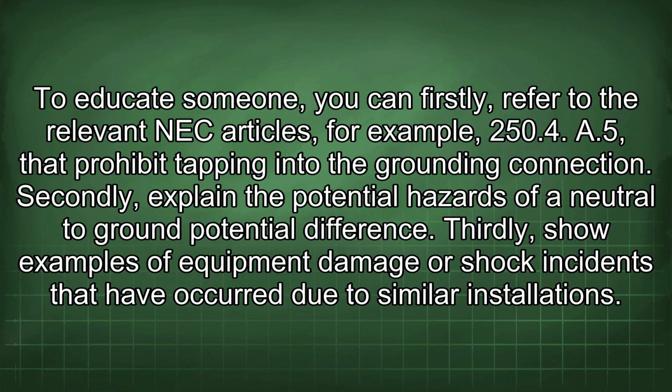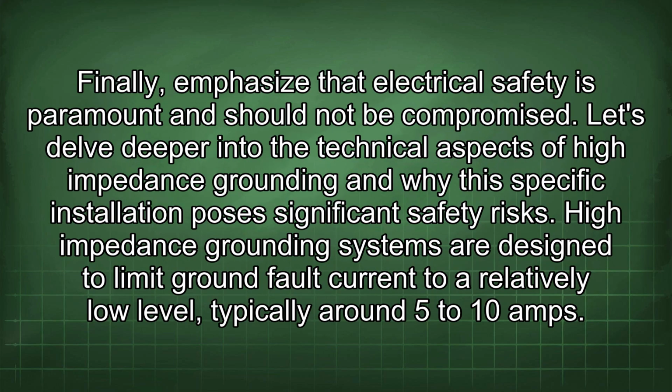To educate someone, you can firstly refer to the relevant NEC articles, for example, 250.4(A)(5), that prohibit tapping into the grounding connection. Secondly, explain the potential hazards of a neutral-to-ground potential difference. Thirdly, show examples of equipment damage or shock incidents that have occurred due to similar installations. Finally, emphasize that electrical safety is paramount and should not be compromised.